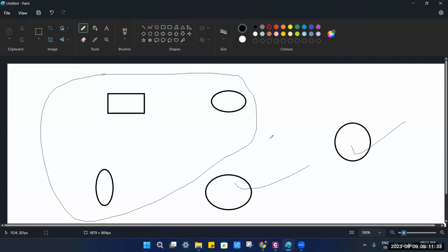Earlier what we were doing, we had to add some repeaters, right? This data will be fetched here, and the repeater will broadcast, that is, extend the range of this router. But that will increase the cost, and if it is a limited area, then you can add one repeater. But if you want to cover a whole city, you cannot put so many repeaters because it will increase the overall cost, right? And in an embedded system, you have to make a product in which the whole deployment cost would be very less. So rather than using this topology, they started using mesh topology.